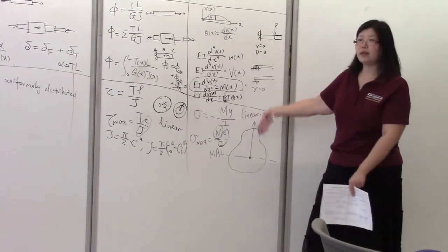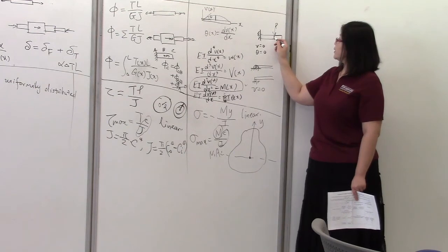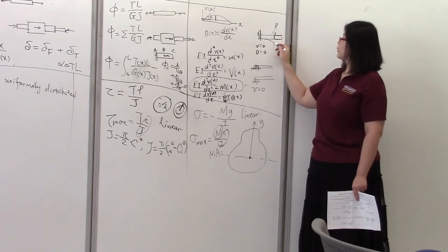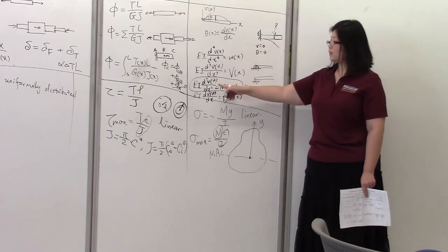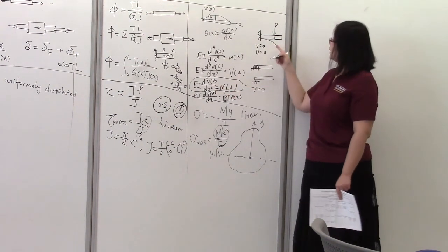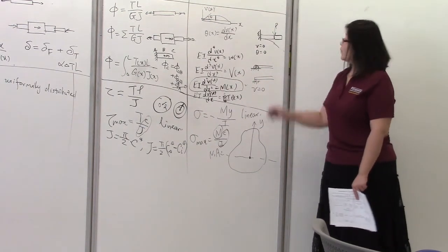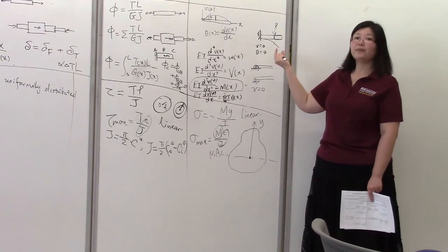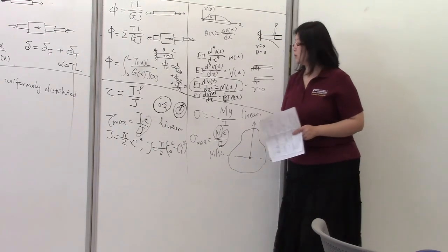So you have 2 sets of integrations, and at this point, the deflection curve should be continuous. Therefore, the deflection determined from the integration of the first second-order differential equation should match the deflection obtained from the second segment of the curve, and the slope is the same. So those are continuity conditions.